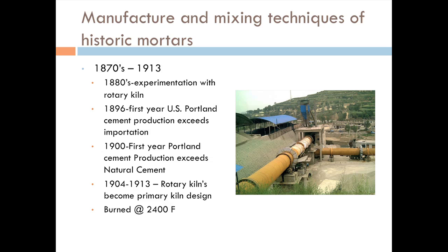Like I said, the lime takes a while to get hard. It stays flexible. Cement can take only a few days, or 28 days would be a standard for building construction. But you might not be able to lay another story of brick as quickly, because lime is slower setting and its compressive strength isn't quite there.